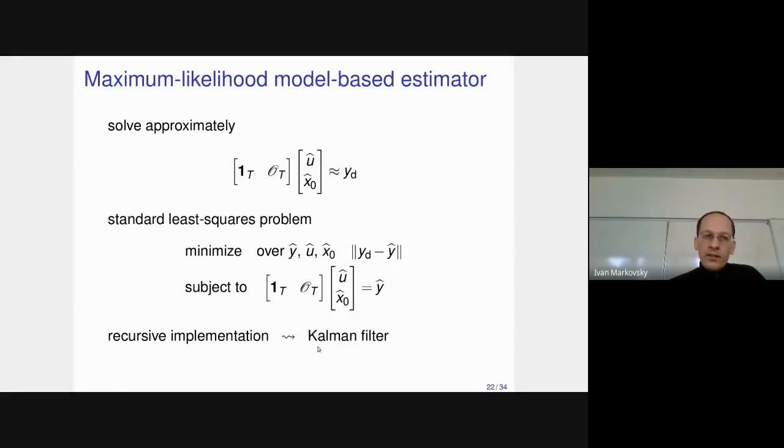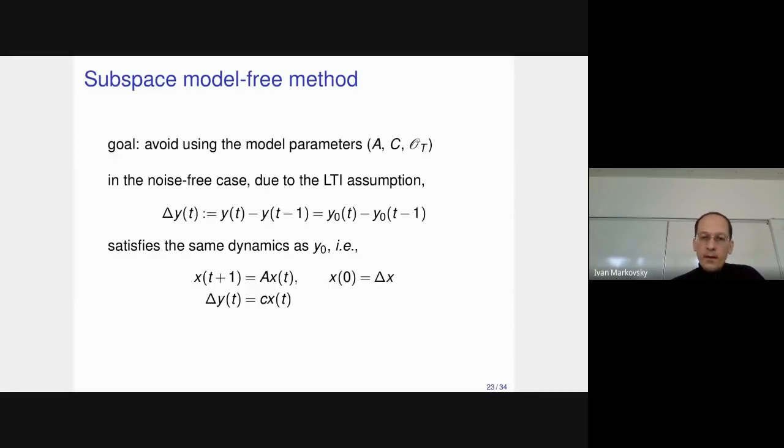So we have a readily available solution for the problem of dynamic measurement, provided we have a given model. What will be the solution now if we don't have the given model, which is what I argued is the real situation? We can first identify the model, and then using the model, apply the Kalman filter. This is the model-based approach. But we can do another thing, which is a data-driven approach.